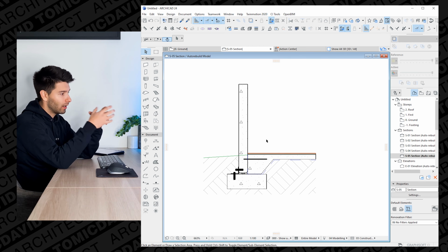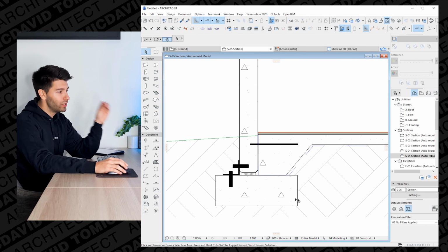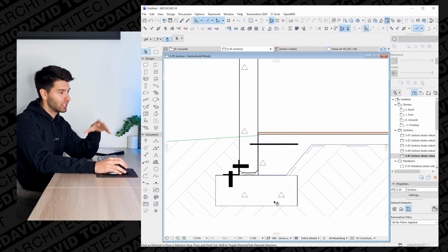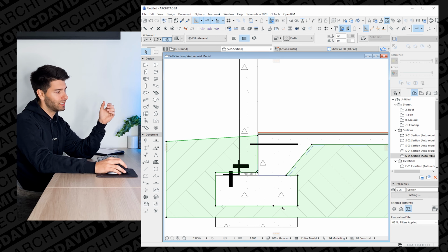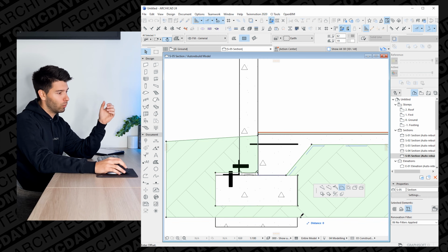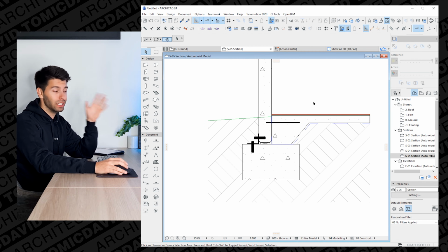Now from a construction detail point of view, that is the fundamentals of how a tilt-up concrete wall would connect to the concrete slab itself and the footing. That footing would be significantly deeper. It would be something along those lines. It would definitely not be a small footing because that concrete wall is very big and very heavy.